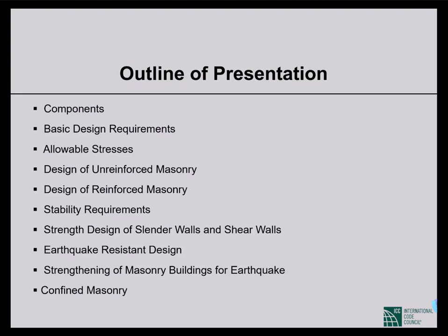You can actually model this by plane strain elements. If you use the finite element method, then usually we use plane strain elements as wall elements, and from the model you can get the stresses.